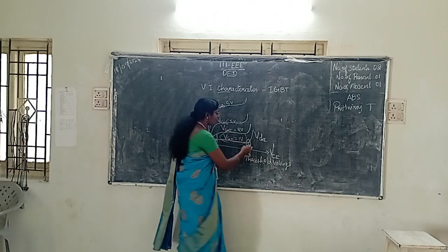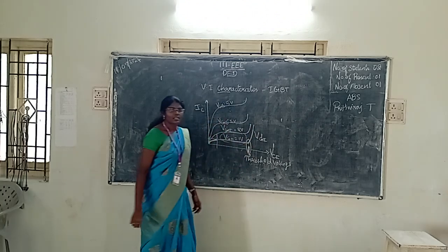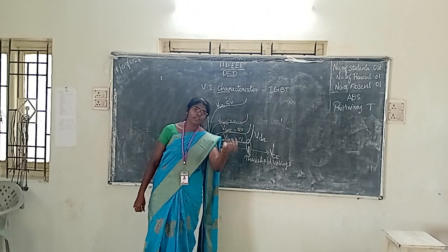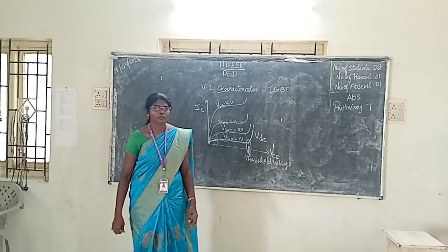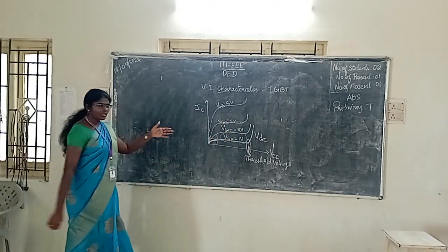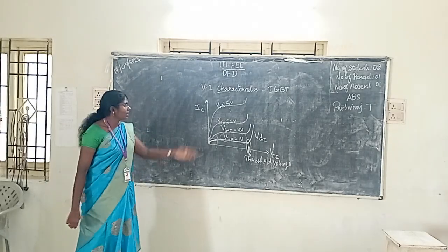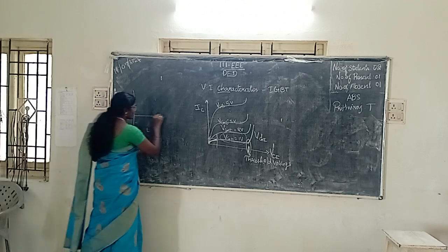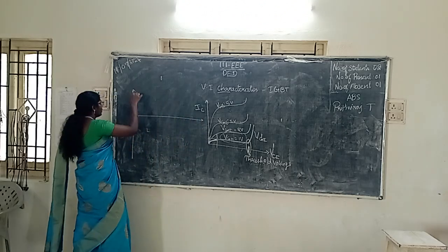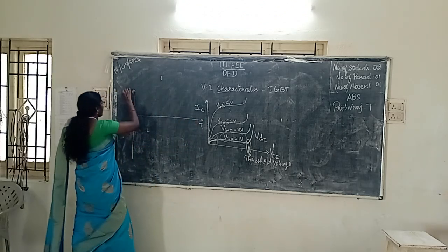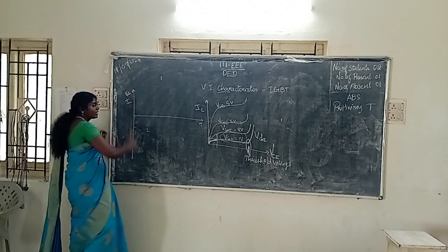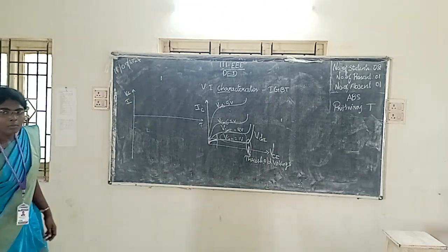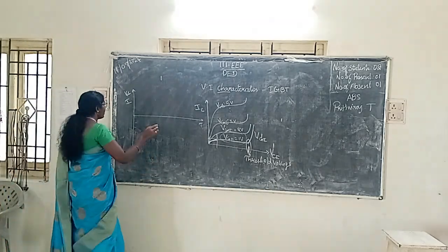Beyond the threshold, the current will increase drastically. Sometimes when it goes to the peak, the device will burst. So this is the VI characteristics of the IGBT. Next, we see the switching characteristics, with respect to time, how the voltage as well as the current behave. We will call this the switching characteristics, about the switch during the on condition and off condition.